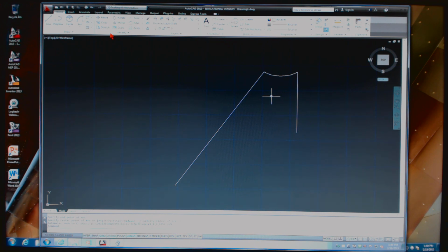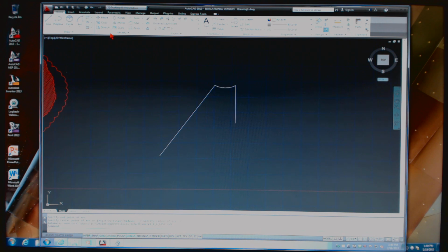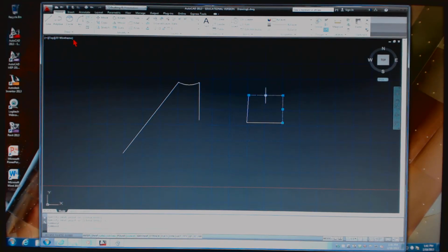If you draw the same square, which works the same way as the line command as far as how you do it, with a polyline, it's going to be 1 piece, like a rectangle basically. Okay, and I'll show you the difference. I'm going to draw a square with the line command. And you can see it is all 4 individual pieces.